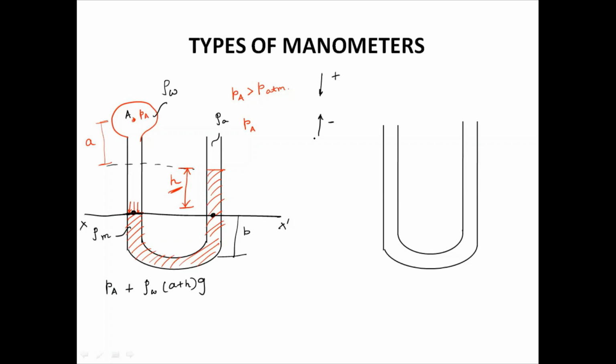Already you have seen the equation dP/dz is equal to minus rho g, the hydrostatic law. So if you go downwards, what will come? Rho m b into g. You come here, again you go up, so rho m b g. The same pressure, so it is cancelled out. So it is better to say that here and here is the same pressure.